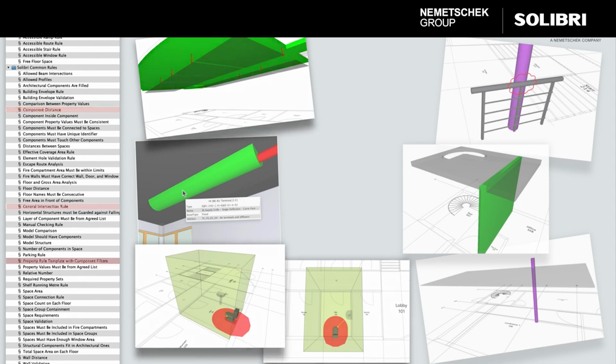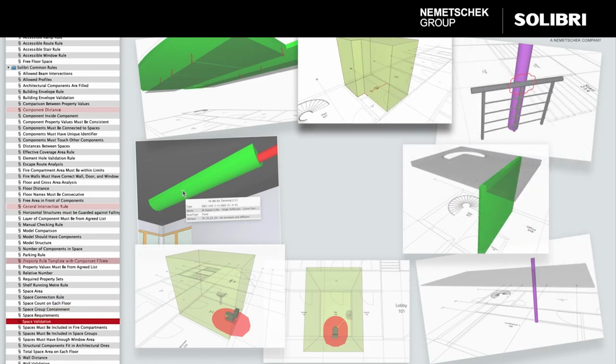Spaces can be evaluated using the space validation template. This ensures rooms are fully enveloped by boundary components, such as walls, floors, ceilings, or roofs without boundary gaps. Spaces in the model may be used for many purposes. If they provide incorrect perimeters, areas, and volumes, reports in line with the schedule of accommodation through to providing component locations for planned preventative maintenance tasks will be inaccurate.